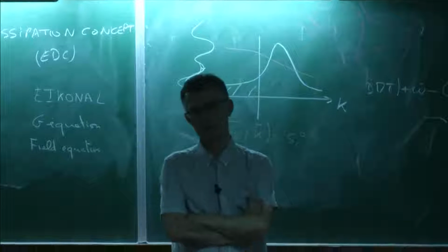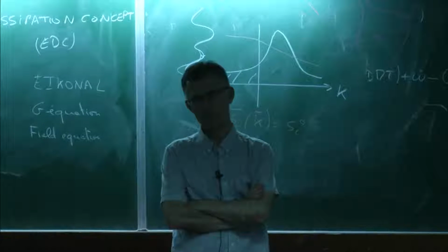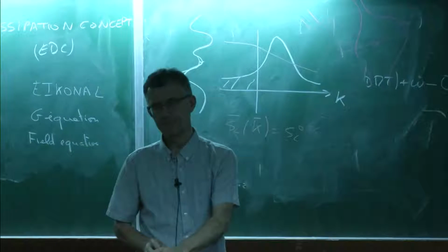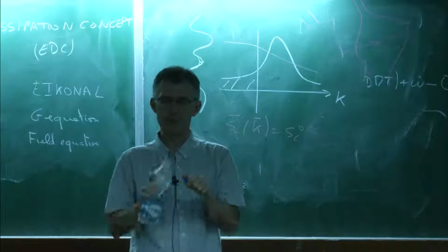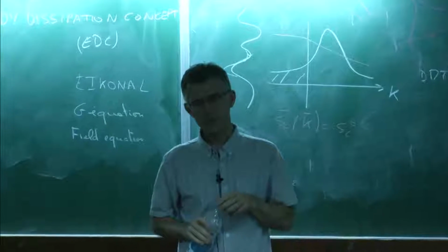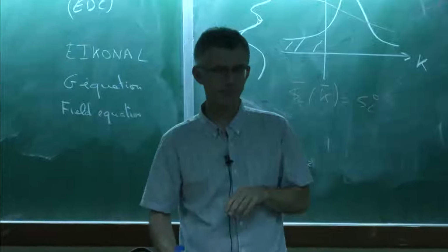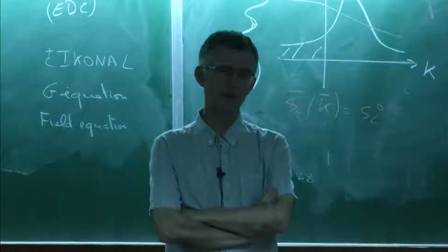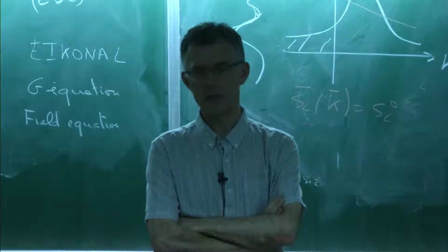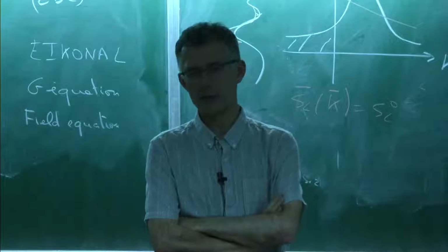Actually, I'm interested to do some simulation for the stratified combustion. You know that the equivalence ratio is changing, and could you suggest how to approach this using some blended kind of model? Yeah. I think that if you do a premix flame, it's sufficient to take into account stratification, not stretch. I would start with stratification alone.